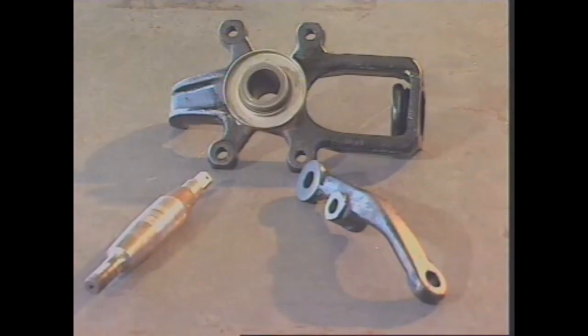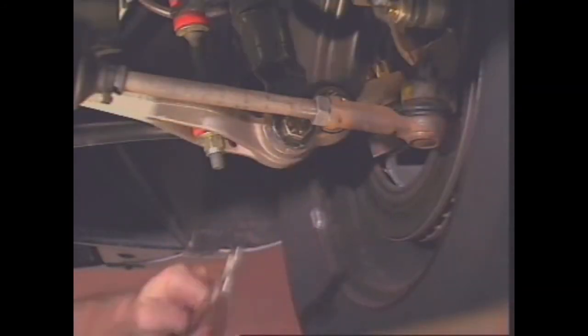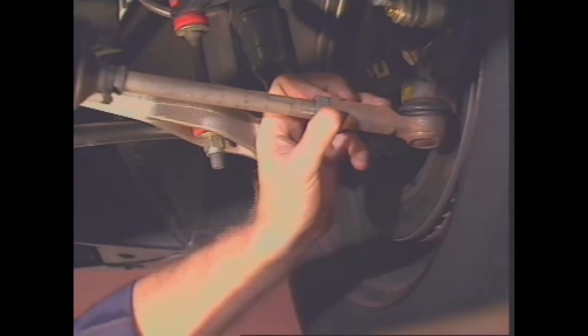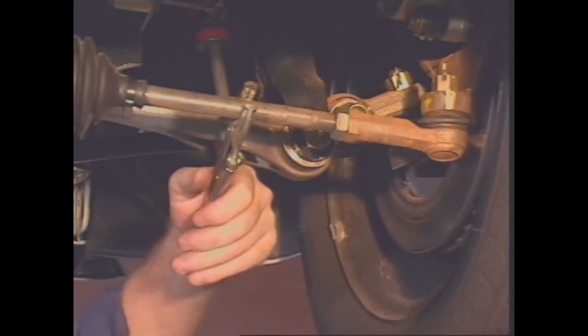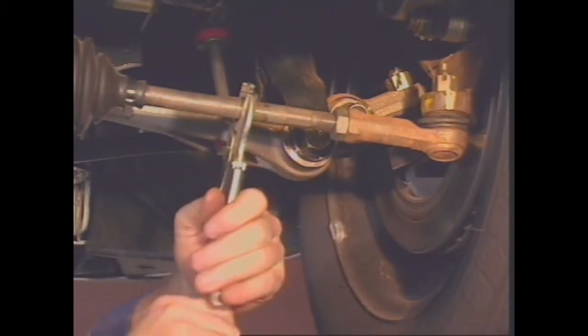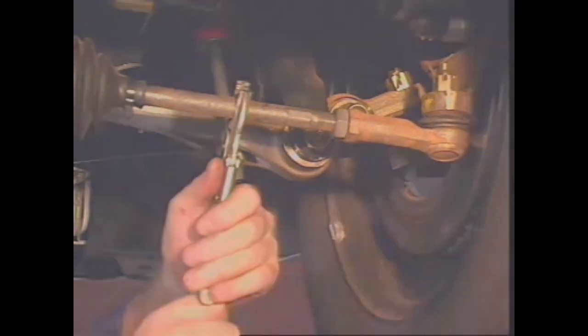The lever, the stub axle, and the stub axle carrier can be forged as one piece and can be referred to as a knuckle. They can also be made as separate units and assembled to form one piece. Each steering system makes provision for adjustment of the linkage to achieve the manufacturer's recommended toe setting. The track rods or tie rod ends are threaded to provide for their lengthening or shortening.